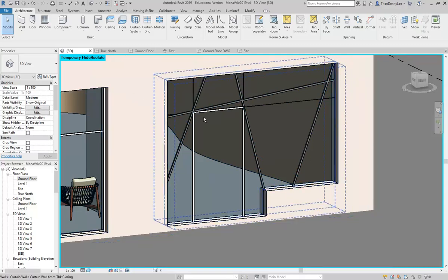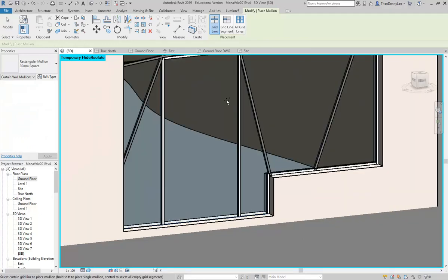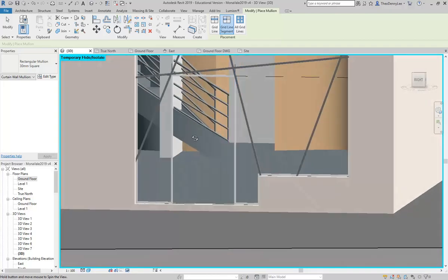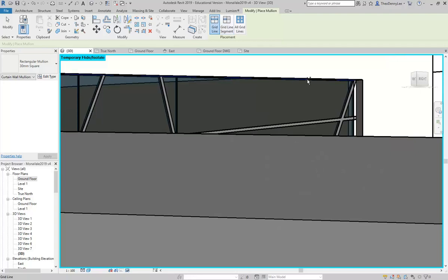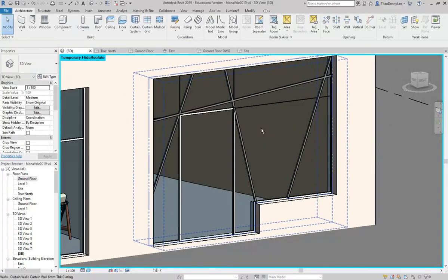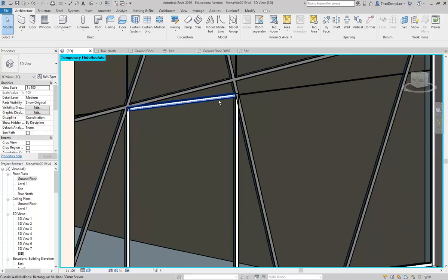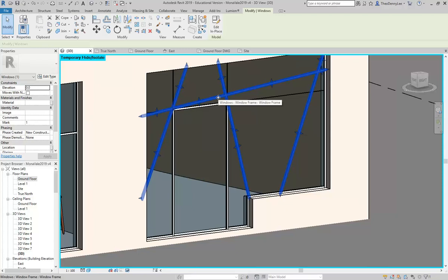So maybe just to see what you're remembering, I'll put some mullions just on the outside just because I want it. And here, now, notice I'm not putting a mullion at the bottom of the door, of course. We don't want people to trip on that. But then what I was going to see, if you remember, is how we change the material of the thing that I've modelled. So this frame here, the one that's come with the mullion, it's got a material already. But the one that I modelled, that was model in place. So do you remember how to change the material of anything you make with model in place?